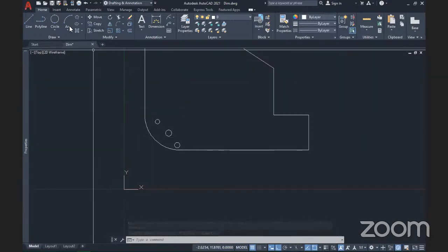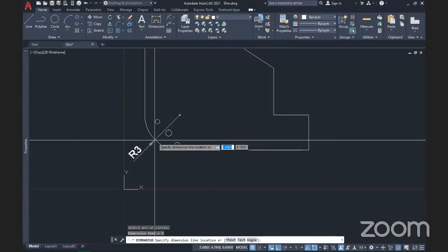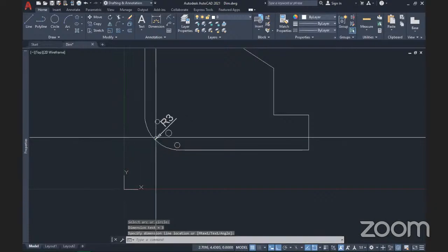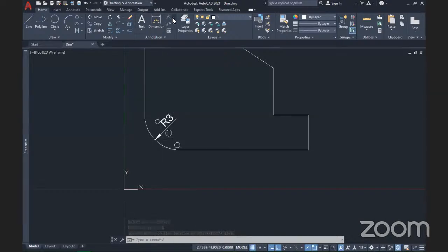I had all these things on, and I don't want to use the normal reduce dimensioning, because if I try to use it, it will in some cases, let's say this is where I want to drop it, cluster this area, and I don't want it to be like this. That is where the jog dimensioning tool comes in, because now you can decide where you want to use as your center point, but you know that this is not the real center point. The real center point is somewhere else, and it gives you the perfect radius of that object.